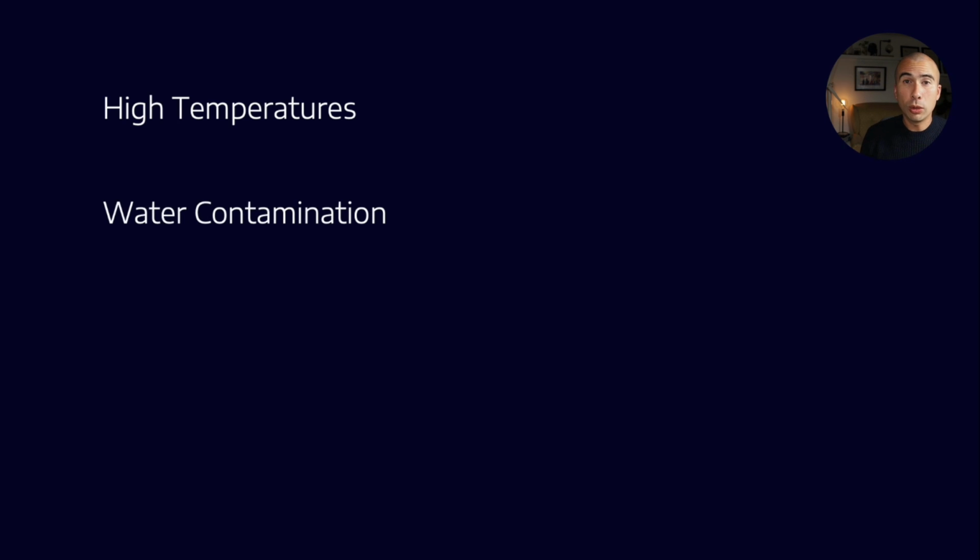We often have water contamination. So water contamination is present either in the environment, think of offshore wind turbines having to deal with sea spray. It could be paper mills, for example, which often have a lot of humidity and moisture in the air. So we often see a lot of water contamination. We often see particulate contamination. Think about gear sets at mine sites, for example. This is a particular problem for open gear sets, which don't have that much protection from the elements.